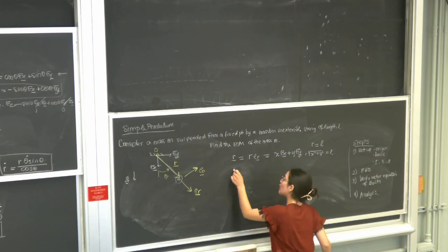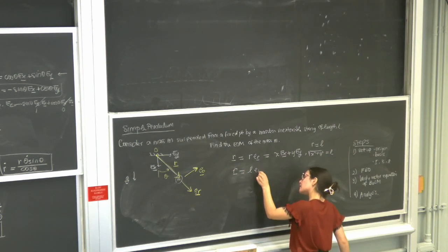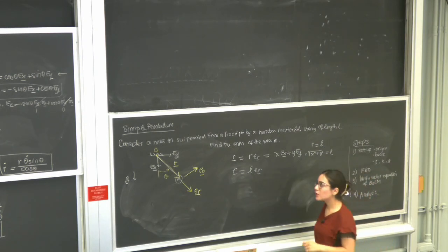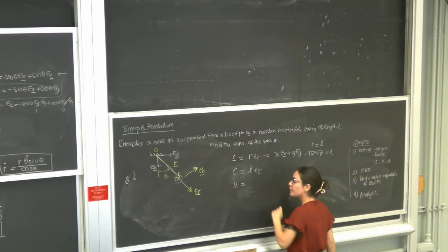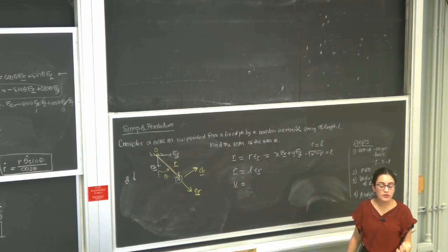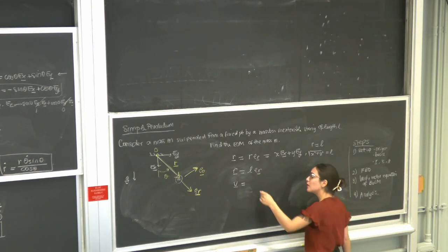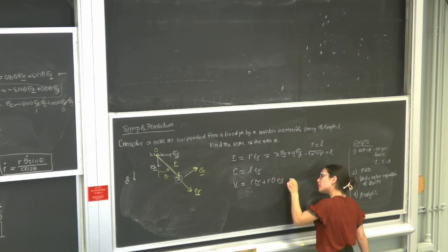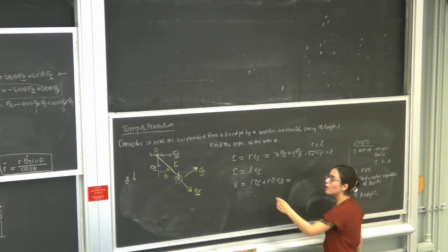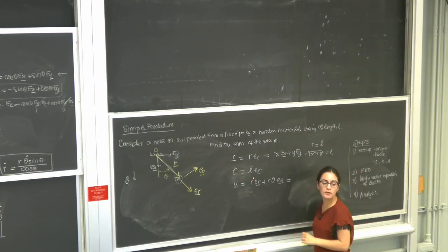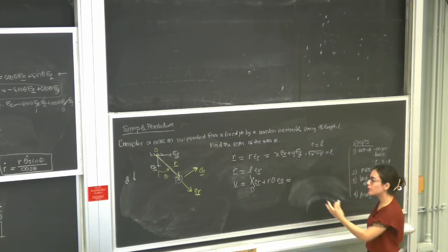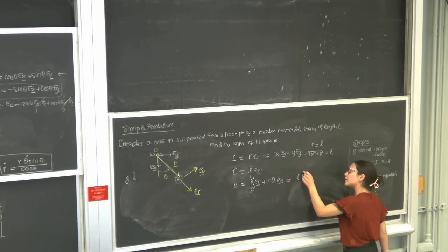So I'm going to say r is L er. L is a constant. So if I wanted to write my velocity vector v, it is r dot er plus r theta dot e theta. In this particular problem, what is r dot equal to? 0. Why? Because r is equal to L. So my velocity vector is just L theta dot e theta.